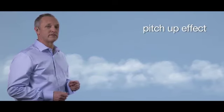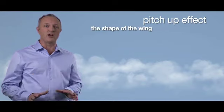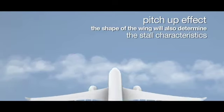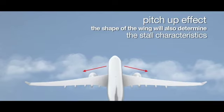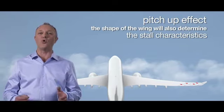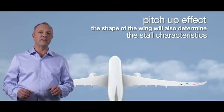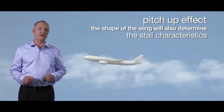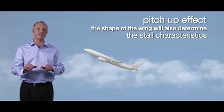Pitch up effect. The shape of the wing will also determine the stall characteristics. Modern jet aircraft have swept back wings. This kind of wing allows higher speed, but it has an increased tendency to stall at or near the wingtip first. The loss of lift at the wingtip moves the center of pressure forward, thus inducing a pitch-up moment.